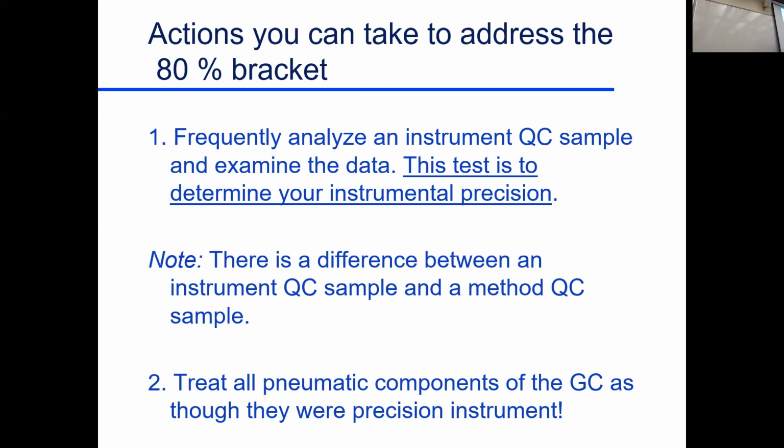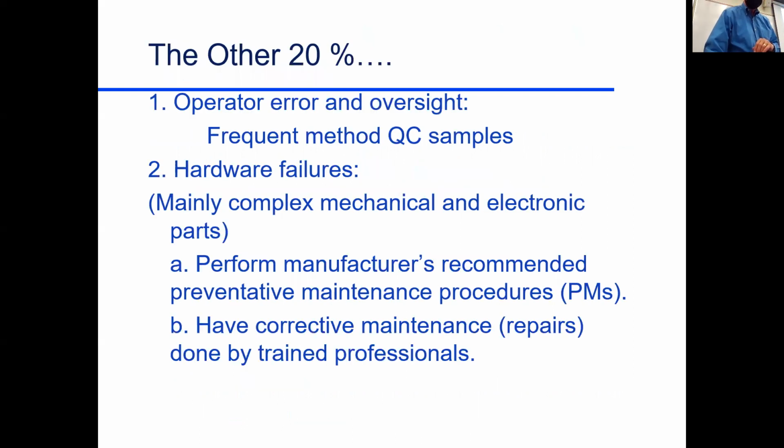I think I mentioned this already. You're managing gas flows. You have to control the flow rates. You have to control the pressures in the system. And again, you do that carefully. The other 20% is operator error, oversight.